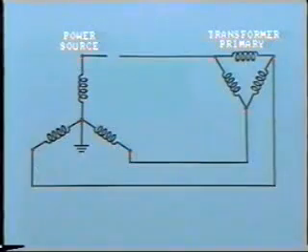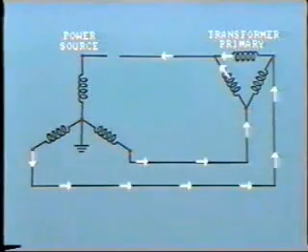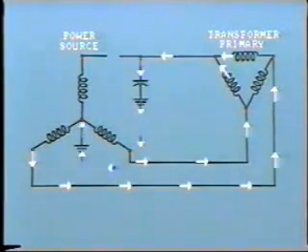In the interim period, the transformer is still connected to the other two phases, and currents will circulate in this manner. The return path to ground is through the capacitance of the open line.